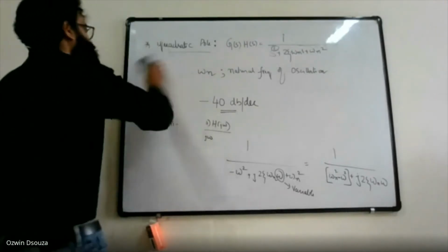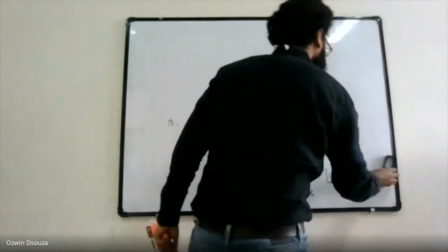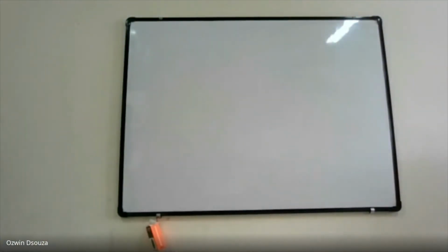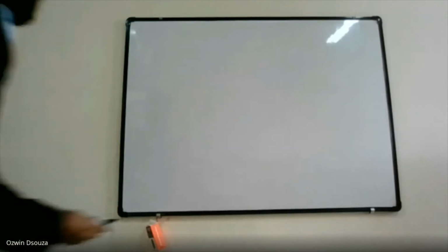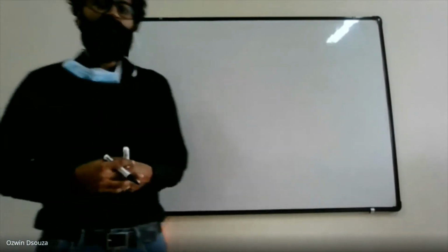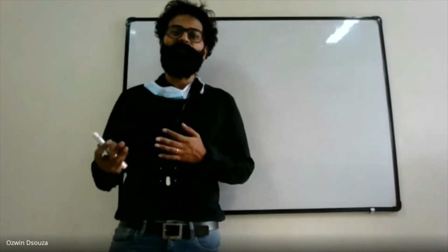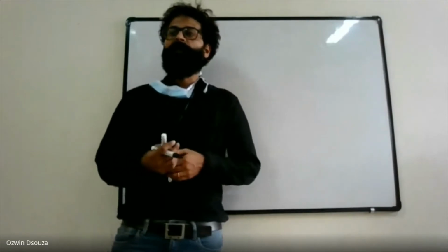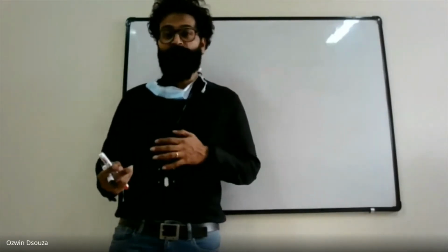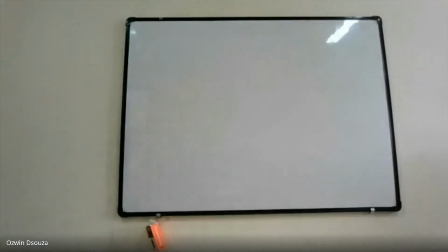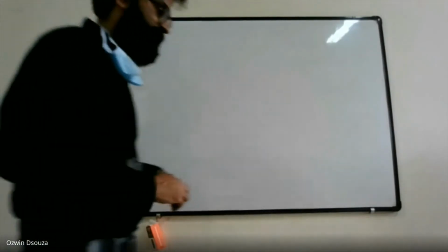Okay. So a similar expression can also be written for a quadratic zero. Wherever you have a negative sign, you replace it with a positive sign. I think you will be able to comprehend the situation. So a quadratic zero you can handle with just the positive sign. The slope you take as plus 40 decibel per decade, and for the angle, you write tan inverse with the plus sign. That's all. Fine. So that's it from the basic factors side.